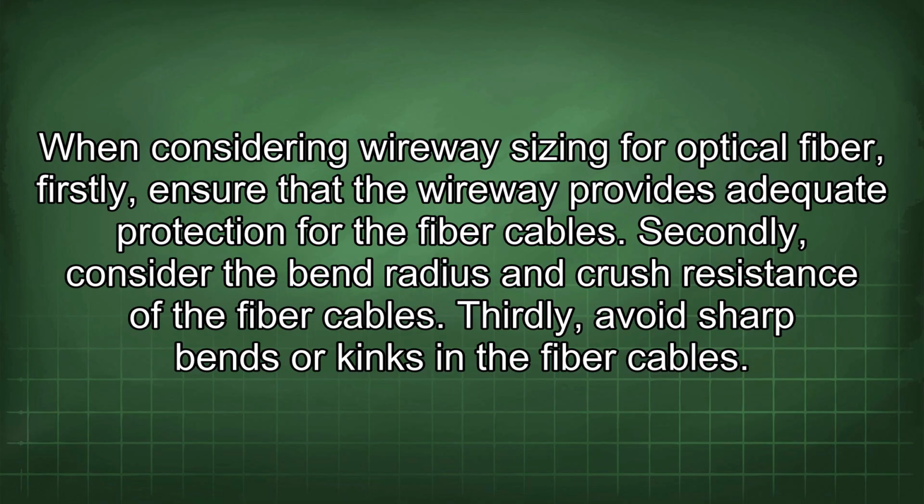When considering wireway sizing for optical fiber, firstly, ensure that the wireway provides adequate protection for the fiber cables. Secondly, consider the bend radius and crush resistance of the fiber cables. Thirdly, avoid sharp bends or kinks in the fiber cables.